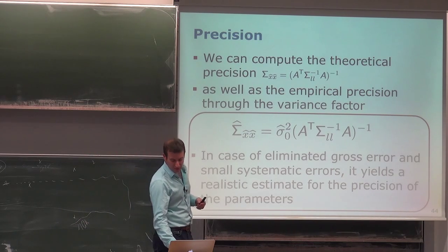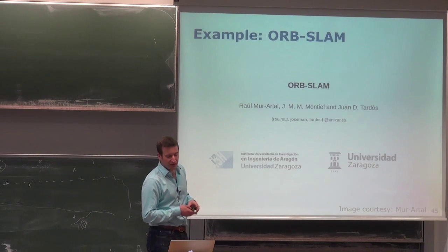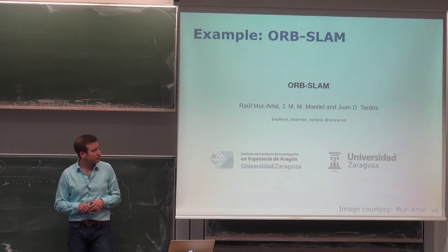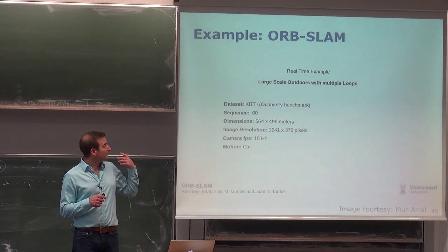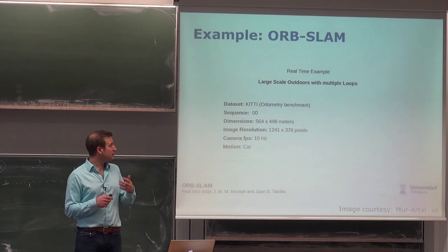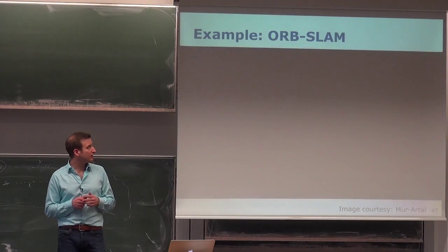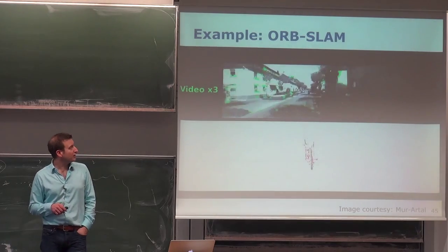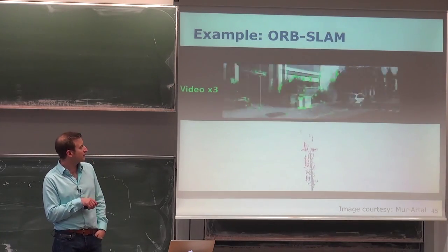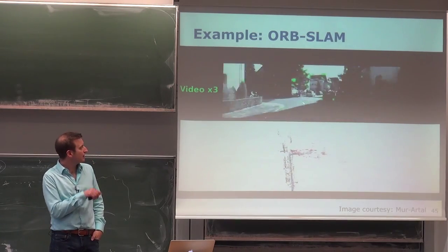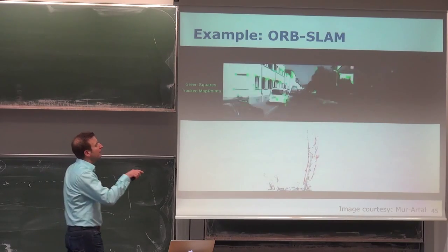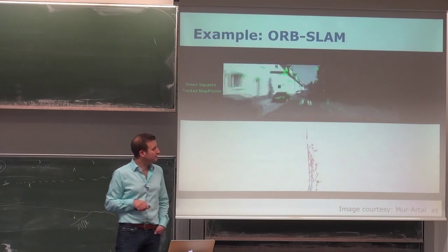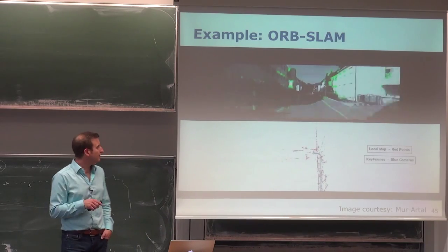And if you put a lot of those things together, one example is a recently published system which does the pose estimation and mapping at the same point in time using camera images on a car data set. This is one of the standard data sets used for evaluating motion tracking in cars. What you can see here is the camera image, the single camera. These are special features extracted from the environment. The goal is that they are very robust features.